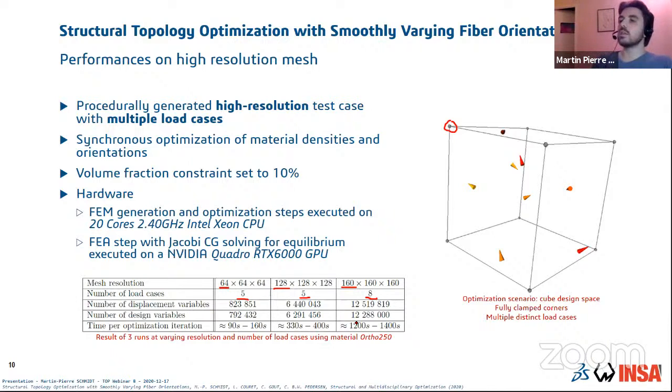Well, the reason why we wanted this orientation field as a fairly explicit definition in the optimization workflow is that if we can model another problem, it could also be used there. We didn't specifically think about vibration, but we did think about thermal diffusion, because then it's fairly easy to have an anisotropic thermal diffusion, and we can also get the gradients fairly easily.